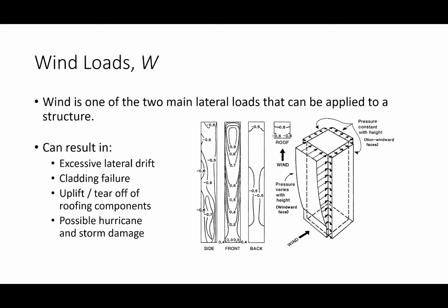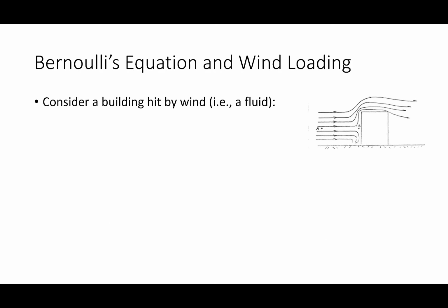We're only going to give a very cursory review of wind forces, but a couple things to keep in mind. If you have a building and wind strikes the building in one direction, you not only generate forces along that face, the windward face, but you'll generate forces along all of the other faces as well. Just some terminology for you, if this is the windward face, we would call this the leeward face. And so that face of the building is going to see an aerodynamic effect as well. Now, Dr. Waite would be proud of this. What we're going to do is go through the base wind speed equation.